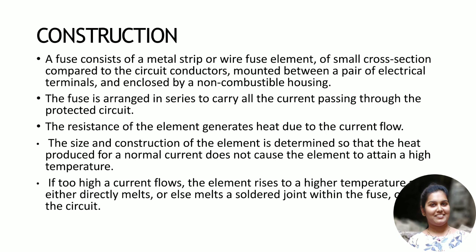Coming to the construction of the fuse, a fuse consists of a single metal wire or a wire fuse element of small cross section compared to the circuit conductor, mounted between a pair of electrical terminals and enclosed in a non-combustible housing. In most cases we see ceramic or any other insulating kind of casing used for the construction of the fuse. The fuse is arranged in series to carry the overall current passing through the protected circuit.